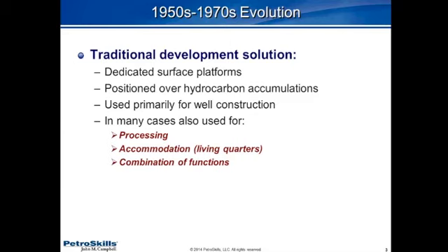This style of development requires that you be positioned over or close to a hydrocarbon accumulation, so the reservoir needs to be close to your platform. Today's drilling techniques permit a reach or horizontal extension from the platform location of perhaps 7 miles, although 4 miles is more typical. Thus, the ability of a fixed point surface platform to reach a reservoir is limited by the distance from the location of the platform to the reservoir.